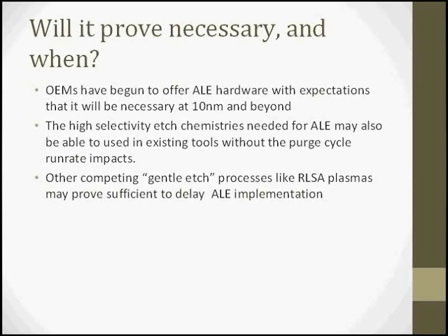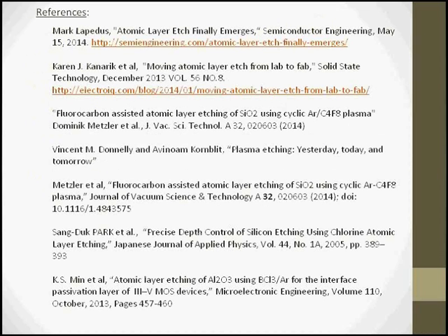However, those etch chemistries may still be able to be used with existing hardware without the need to add the throughput rate impacts of ALE. And other competing gentle etch processes like radial line slot antenna plasmas may prove sufficient to delay ALE implementation.